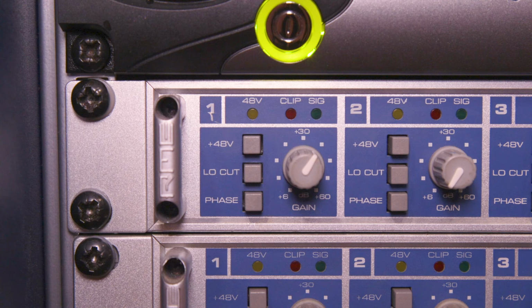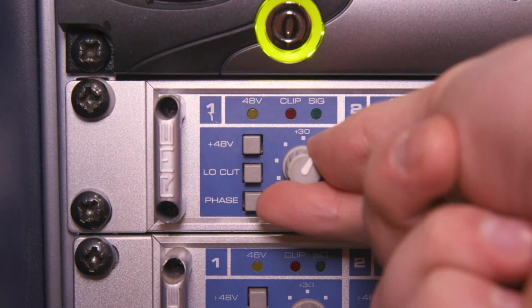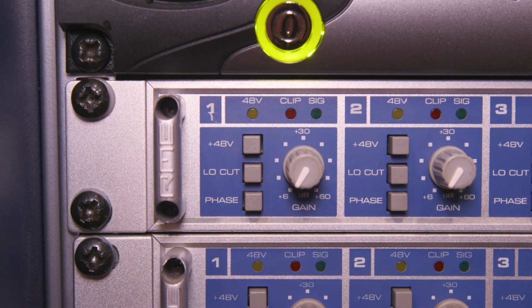Phantom power is required to use condenser microphones. Always turn this off before plugging in a microphone and before unplugging it. You should turn Record Arm off in Pro Tools before using this button as well, because it will often cause a loud pop which could blow the speakers.